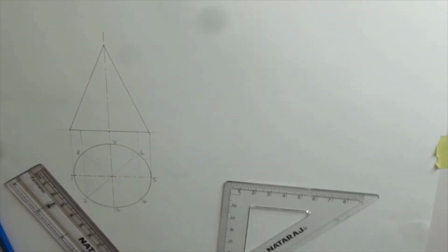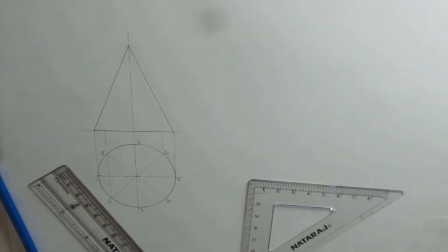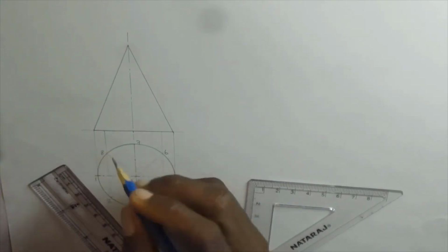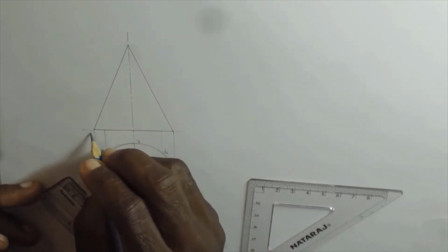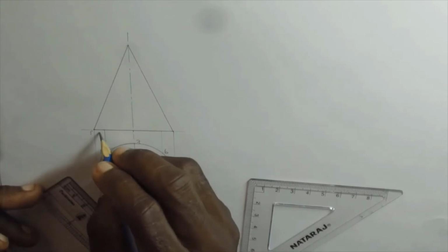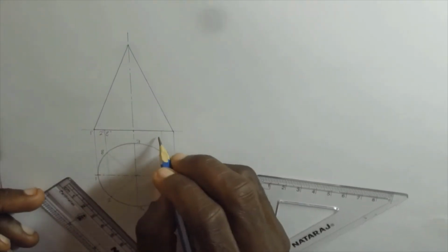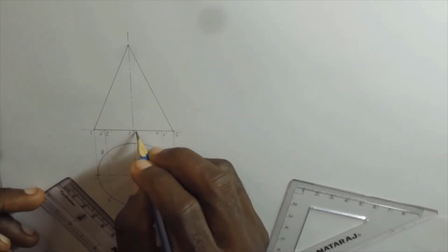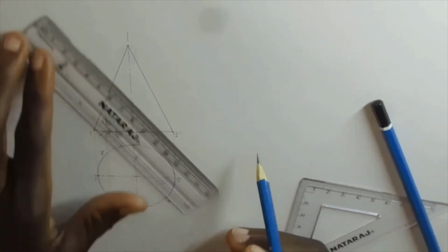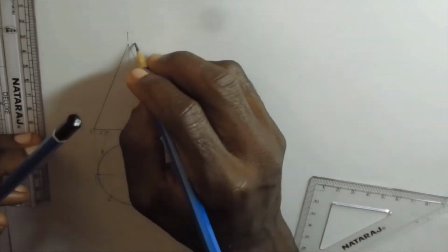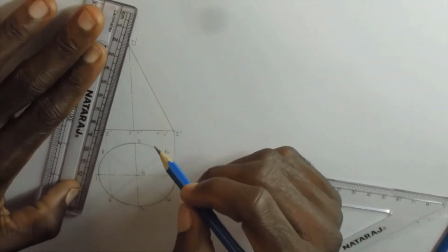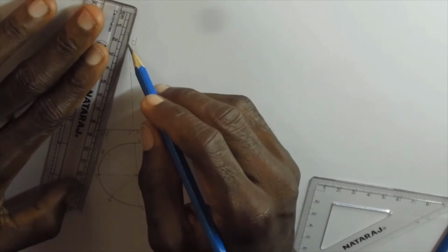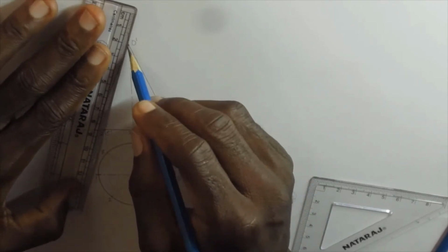Then from here we can label the base of the cone on the front view. So we label them, and we are going to have one projection from 1, we call it 1 prime, and then from 2 and 8 we have 2 prime, 8 prime, and then from 4, 6 we have 4 prime, 6 prime, and then we also have 5 prime, and then the center one, 7 and 3, so we have 7 prime, 3 prime. Okay, and then the apex we use O. So on the front view we have O prime, and on the plan is O.